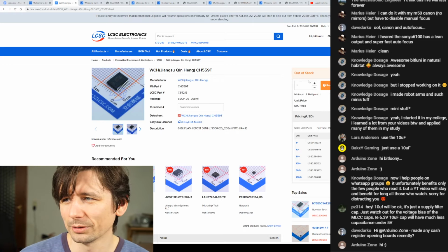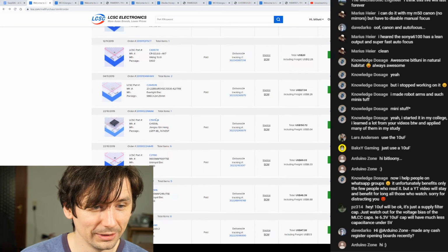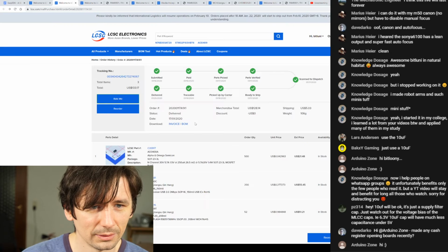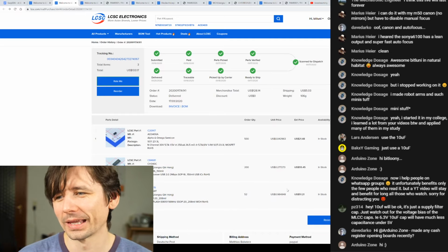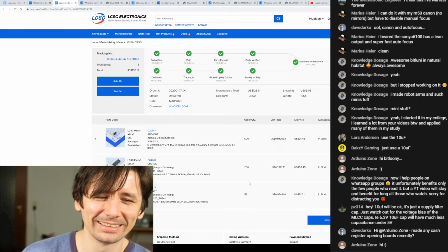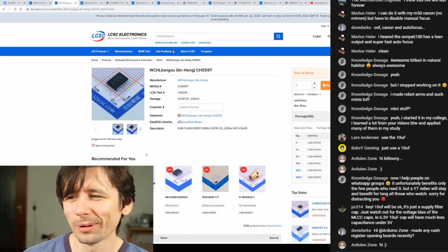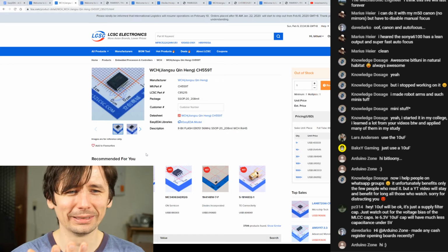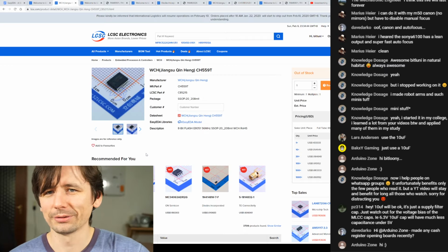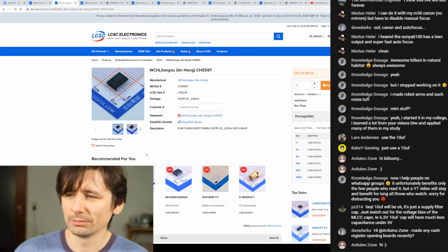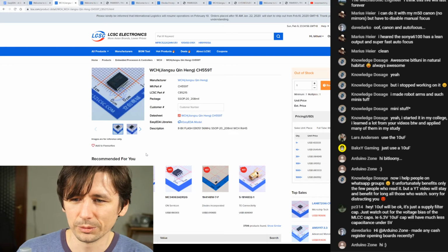And I simply took the complete stock from LCSC, which was, fortunately, only 52. It was still like $51 for me. And then I discovered that this IC isn't dual host. I don't know why they would do that. They have several pins, but it doesn't have the second host. So there is no internal second host. I have used this board with 2 MIDI devices at once, since I want to have some controllers for filters and so on, and then a proper keyboard with some range.